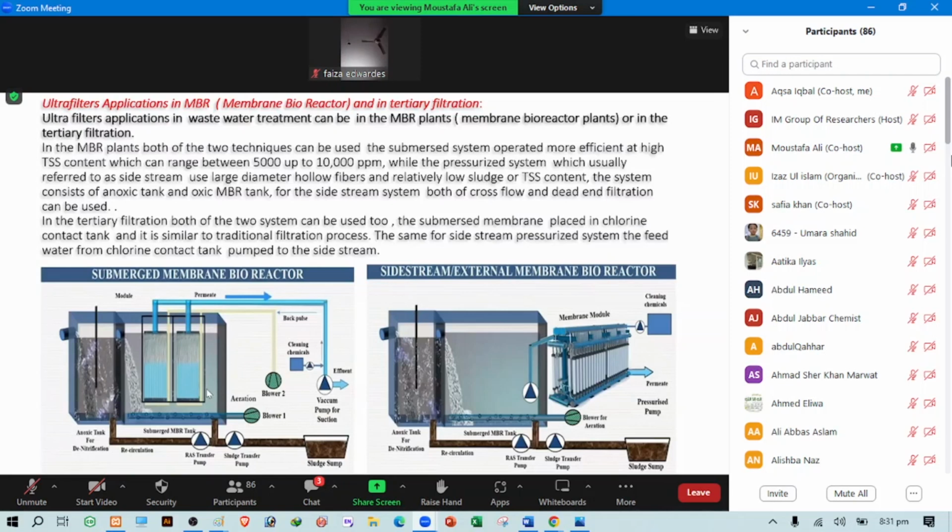We have to pump it continuously at a fixed interval. For example, every 15 minutes, 5 minutes, I will start to pump it to the sludge holding tank, or in the other direction to the anoxic tank. So this is the returned sludge line. This is returned activated sludge. We pump it, as I said, from this MBR tank back, with the organic matter of course in it, again to the anoxic tank for further degradation.